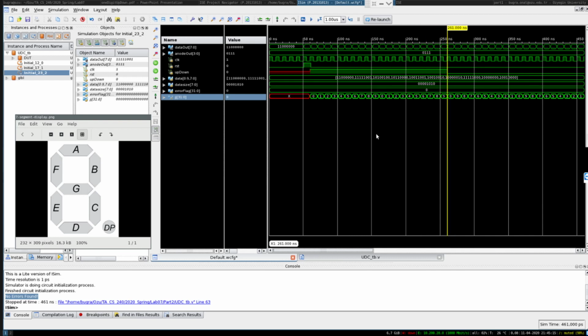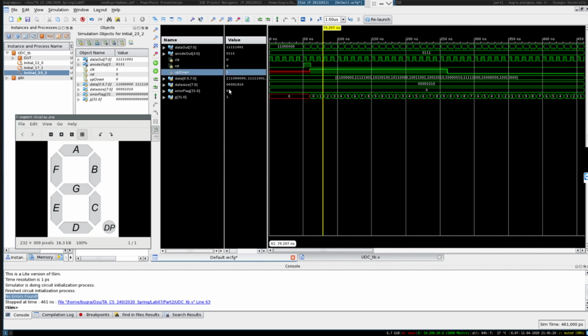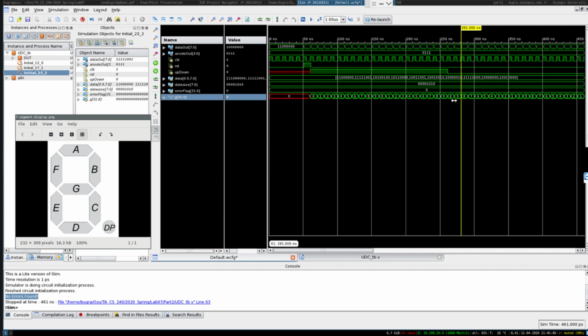And then here, look at this. We have our up-down counter input here. Here, it goes to 0, meaning that now we should decrement. Right now we're at 0. So if you start decrementing from 0, what are you going to get? You're going to have to loop back to 9, and then 8, 7, 6, 5, 4, 3, 2, 1. And if you wanted to check here, only E and decimal point are disabled, so you get something like this, which is a 9.